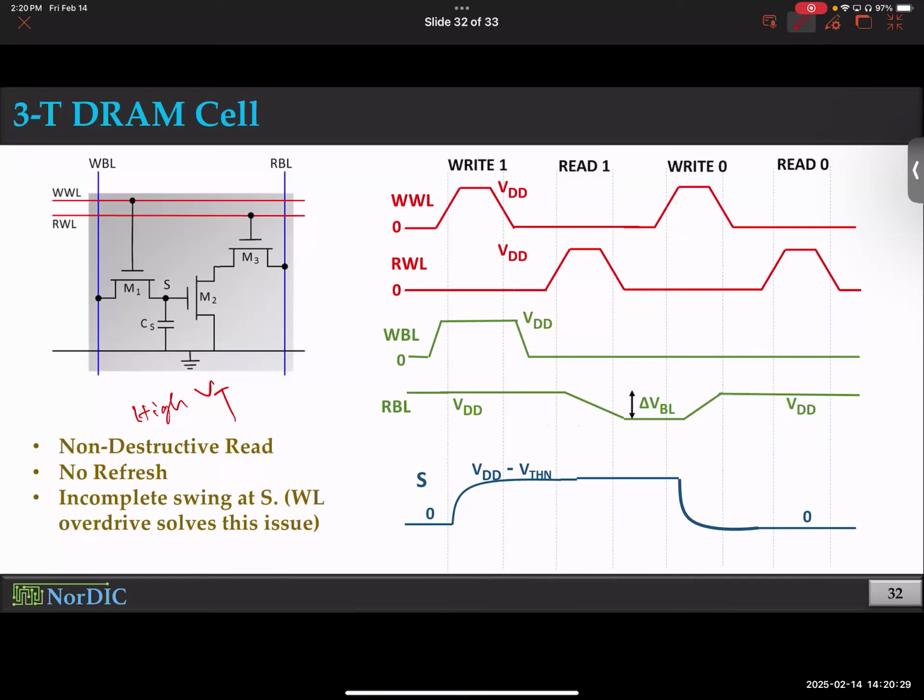I'm not covering it here, but in device courses we cover that threshold voltage changes the leakage exponentially. When you increase threshold voltage, your on current reduces and off current reduces, both. All sorts of currents will reduce, but off current will reduce by an extreme amount, while on current will reduce only slightly, so you can live with it, which is good.